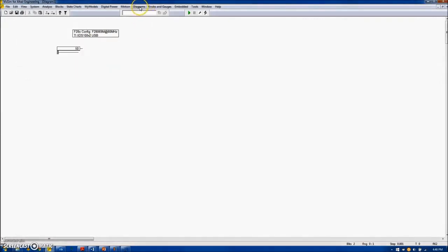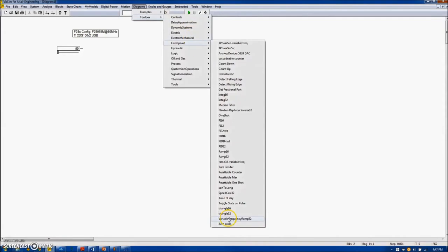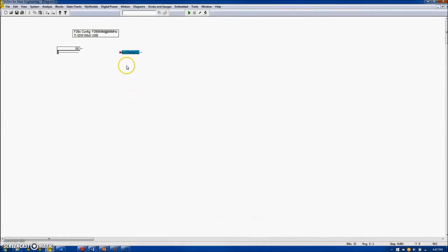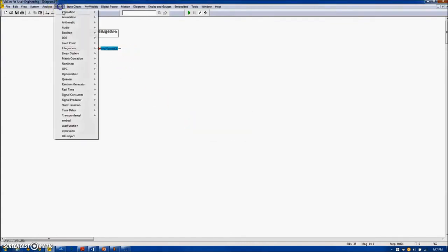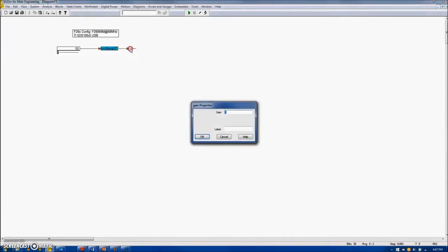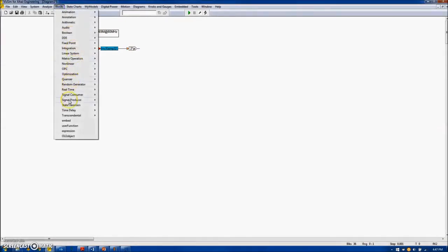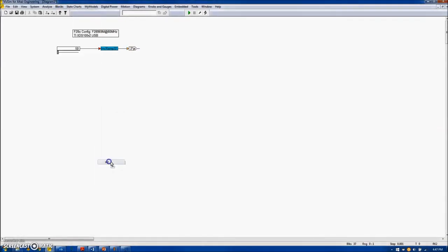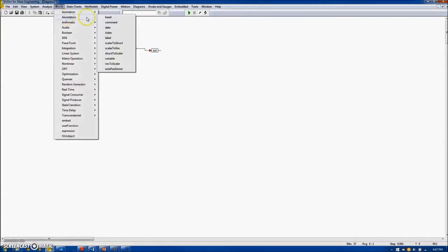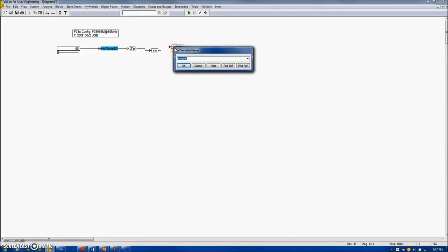Next, we'll create our sine wave signal using a variable frequency ramp 32 block configured to range from 0 to 1, connected to our frequency input with its output scaled to radians by using a gain block set to 2 times pi and processed by a transcendental block sine to produce an output that I'll record in the variable y.